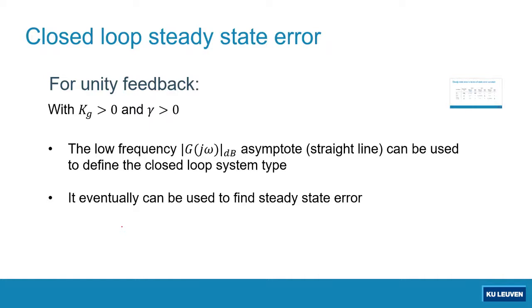Based on the frequency response function, if we have a stable unity feedback system, that means the gain margin as well as the phase margin, both of them have to be positive, right? Okay, we have a positive gain margin and phase margin, which means we have a stable unity feedback system.